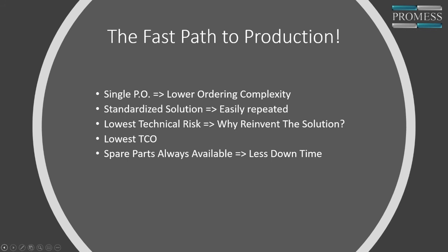So what is used for the resistance for dynamic backlash testing? What I've done in the past is, like I said, it's a 2-axis system, so we're using another one of our torque units for the resistive portion of that to force the gear sets to one side as you're rotating it. We have different modes we can put our torque units into. One is a torque mode that allows it to just put a real-time load on it and maintain that load.